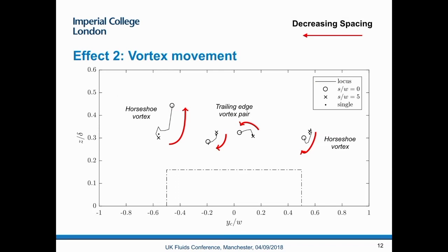When they are very narrow, you get the trailing edge vortex, which is the dominant one in forming your low-speed streak. And these do seem to go up and be more damaging, essentially pulling more low-velocity fluid up into the flow.